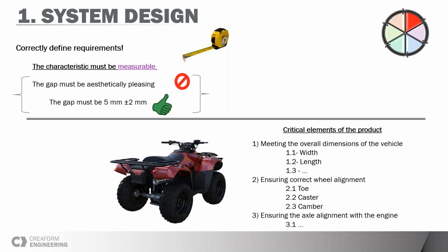Like I mentioned on my last slide, there's a software called 3DCS that we use, but it's a software that makes virtual assembling. It's kind of like a CAD software, but it's really dedicated to dimensional management. So you put your tolerances on every component. Normally in the CAD software, what you would do is just design nominal. So you design everything as nominal and the hole is right in the middle all the time.